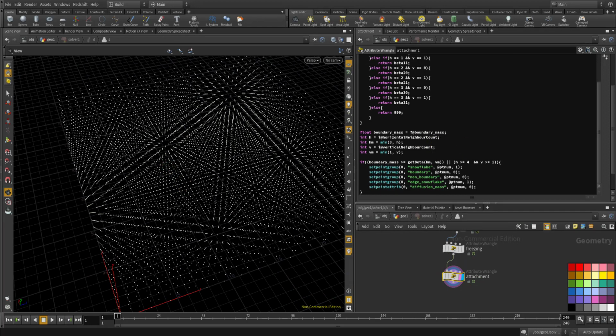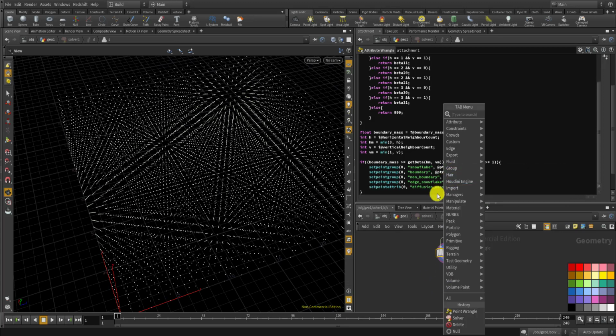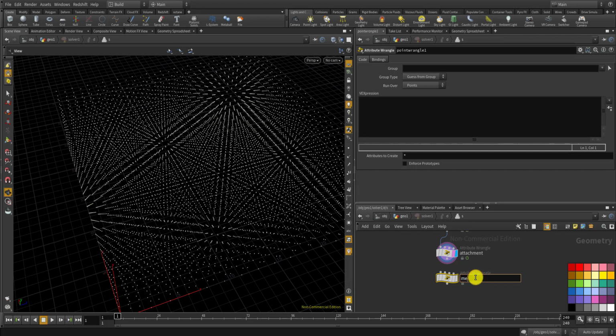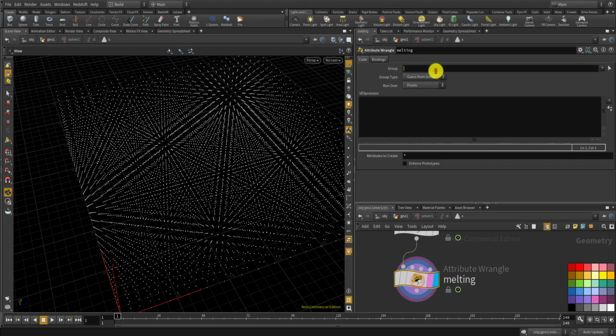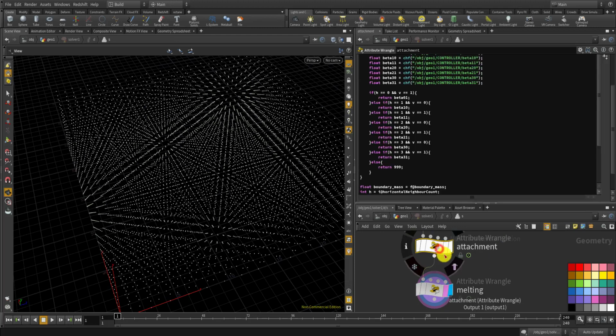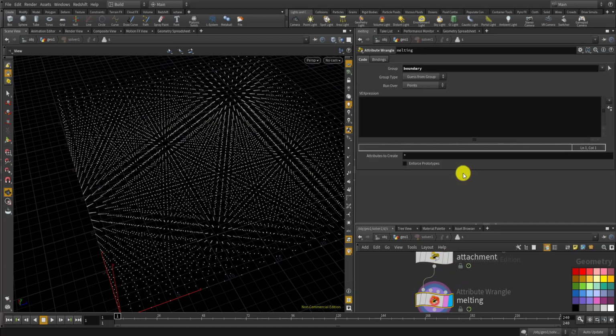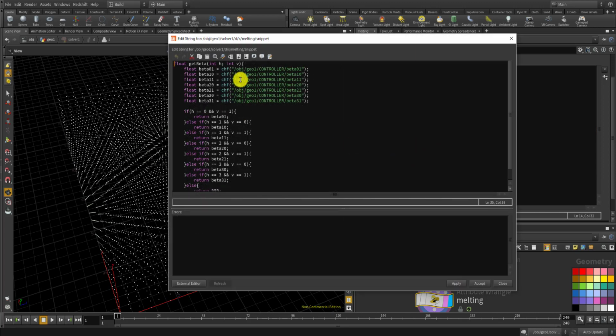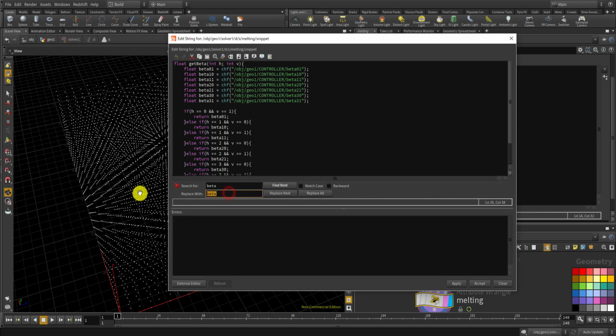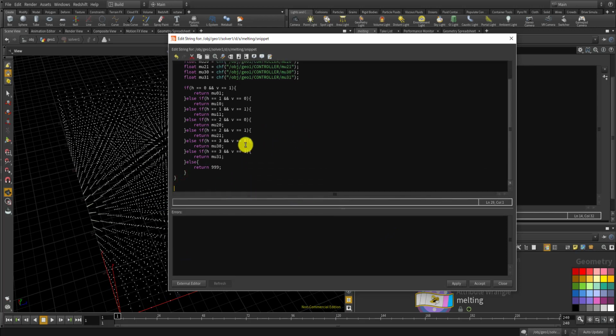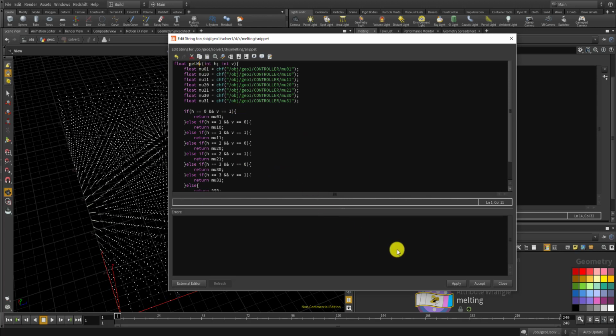Now, let's go to the next update function, which is finally melting. Name this melting, and it will run on the boundary as well. Okay, and this time I'm gonna use a parameter called mu, and let's copy the get beta function from above and paste it here, and replace the beta with mu and replace all. Okay, and name this get mu. Apply.